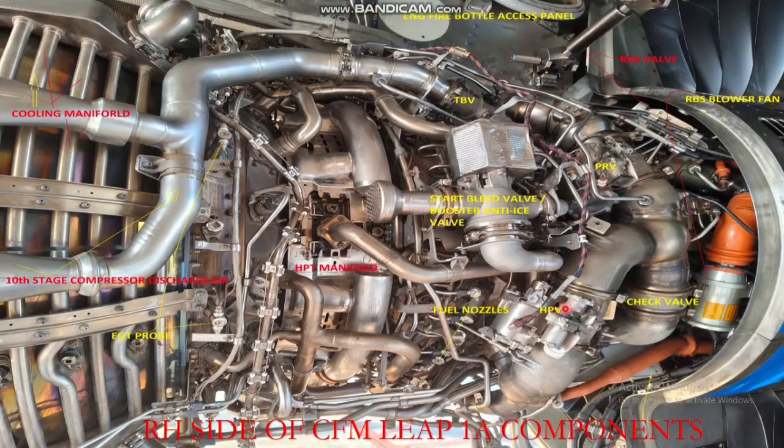HP means high pressure valve. H means high, so you can consider top. So the placarding of the part number will be on the top of this. If you go to the PRV, the placarding of the part number and serial number detail is on the side. So this is on the top, this is on the side. This is just a general physical identification of which is PRV and which is HP.